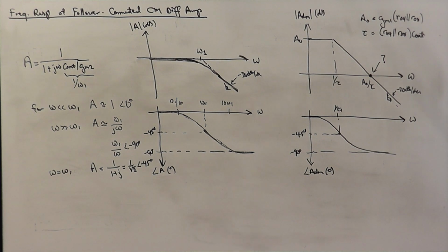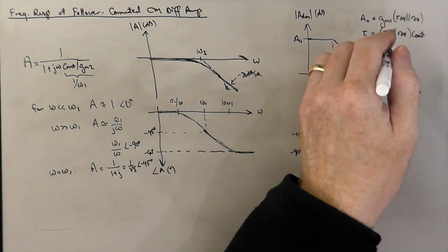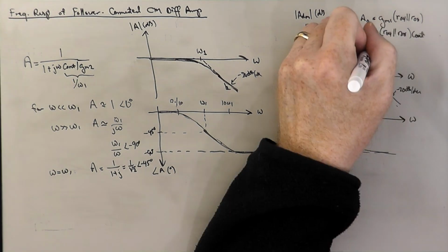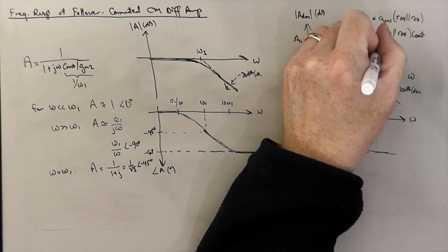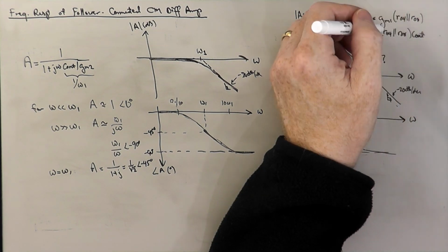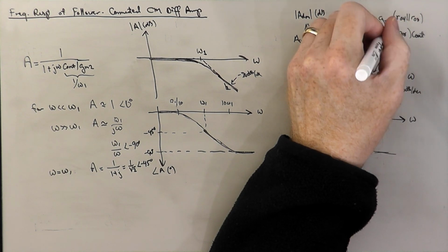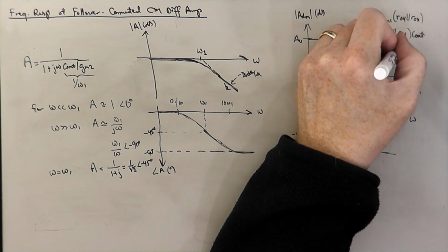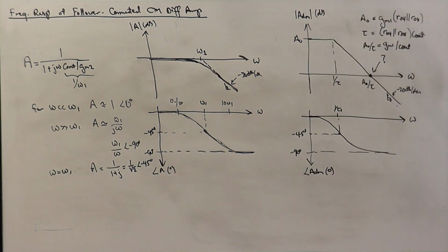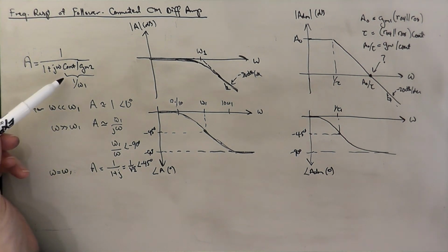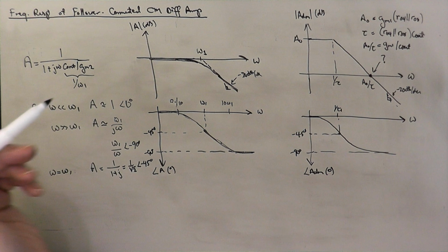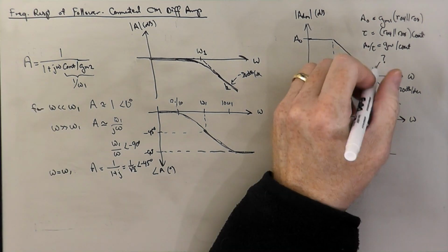Okay? Well, what is A0 over tau? We can just divide these two things. All right, so A0 over tau is equal to, well, the RO4 parallel RO8s cancel, and we're left with GM1 over C out. And if you recall that GM1 is the same as GM2, then it turns out that this frequency is the same as omega 1.